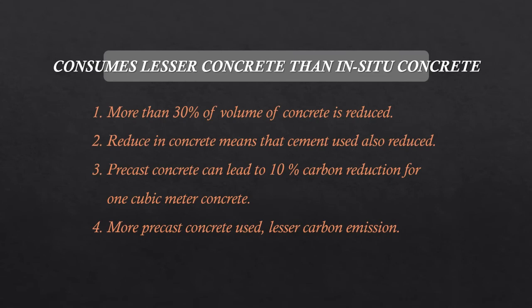Construction with precast concrete consumes a lesser amount of concrete than in-situ concrete. It is found that the volume of concrete is reduced by more than 50% compared to in-situ casting. Reduced concrete means that cement usage is also reduced. The lesser consumption of cement can lead to a 10% carbon reduction for a cubic meter of concrete. To conclude, the more precast concrete used in construction, the lesser the carbon emission.